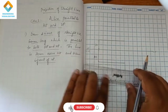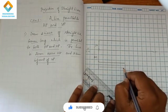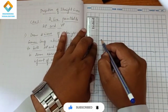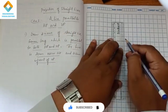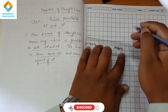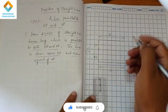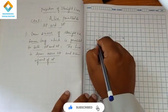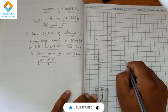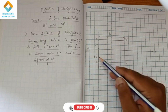This is our top view, which is also 60 mm. This is our front view, which you can name B dash, B dash, and this is AB. So this is line AB of length 60, parallel to both the vertical plane and the HP plane.